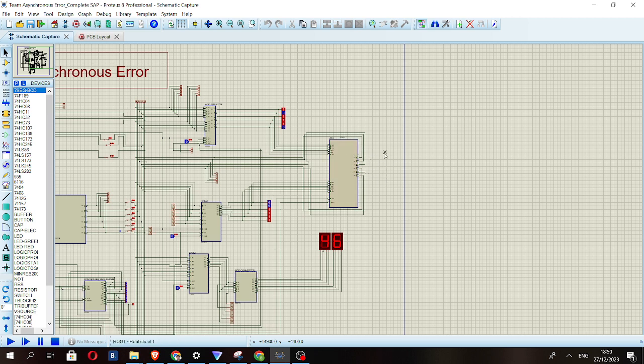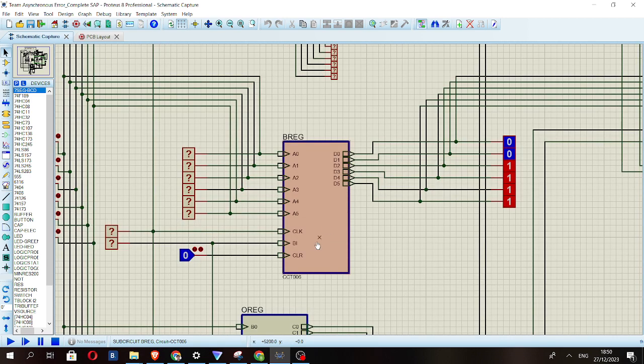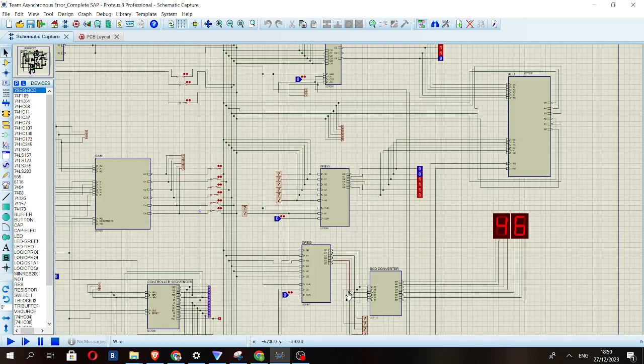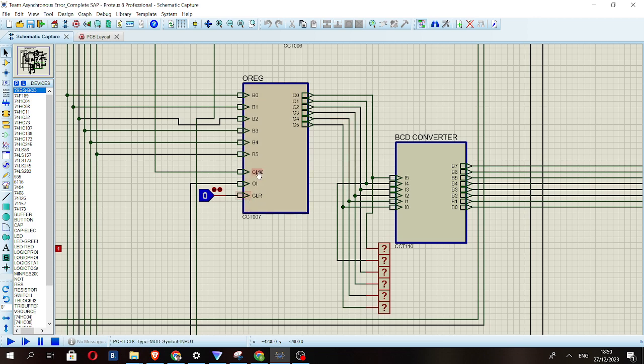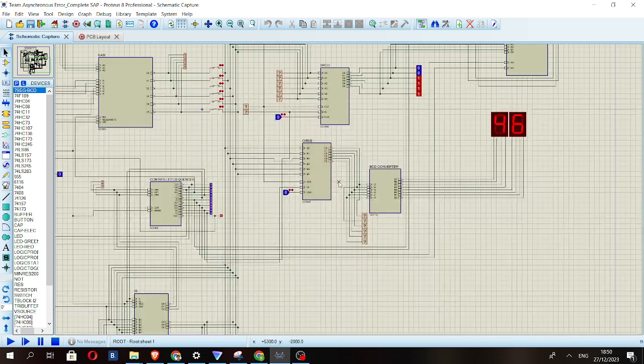As we can see here, the output terminals of the ALU are connected to the output register. So this output register will store the output of the ALU and display it when we request it. Here, as you can see, the OI pin coming from the controller is what decides when the output register displays our outputs.